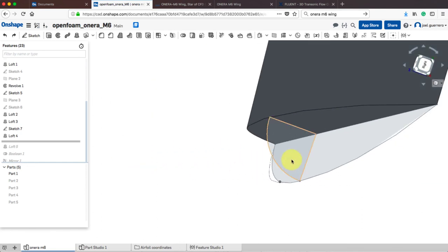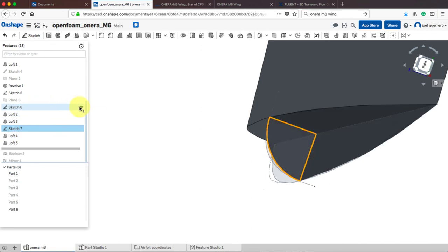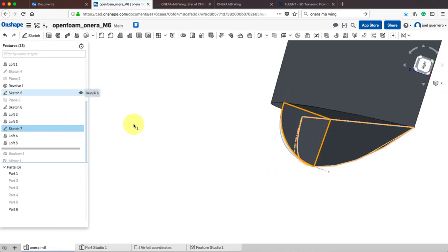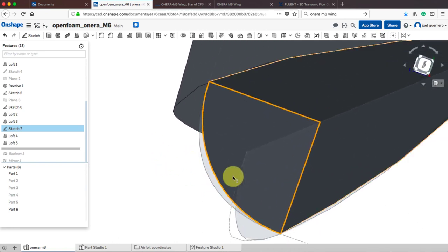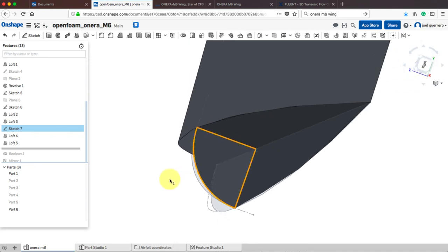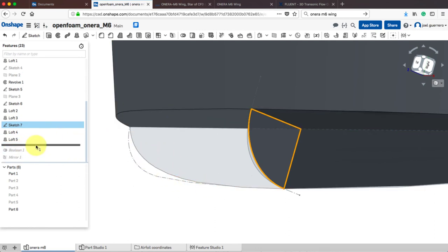So see that I used the revolve to create this section, and then I also did another one, which I think is this one. Okay, so I have a second sketch that I also created using a spline. So this is a little bit different, a little bit bigger, so it's up to you how you want to do it. In this case, probably it would be a good idea not to use the revolve as it will be tangent to this one. And also, if you want, you can add more sections here to have a smoother transition. So you see our final result.